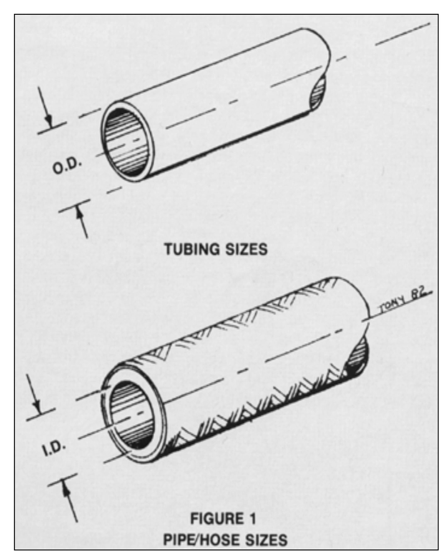What precautions should be taken when routing fluid lines adjacent to electrical wiring? Route the fluid lines below the electrical wiring and maintain a clearance of at least 6 inches whenever possible.